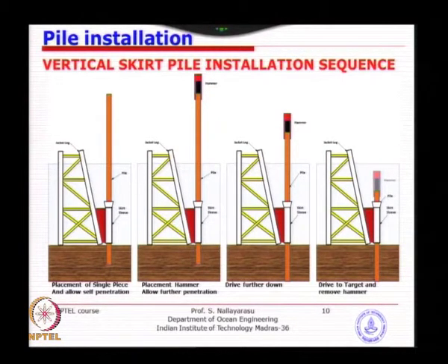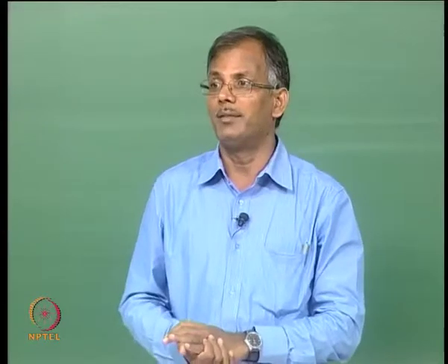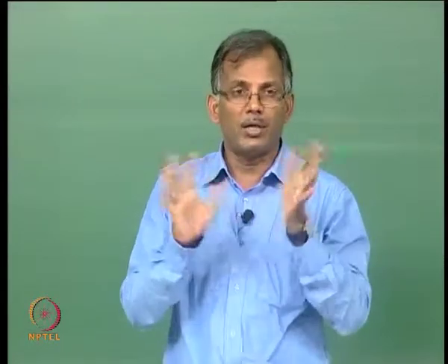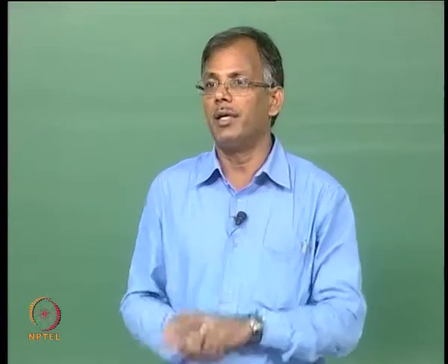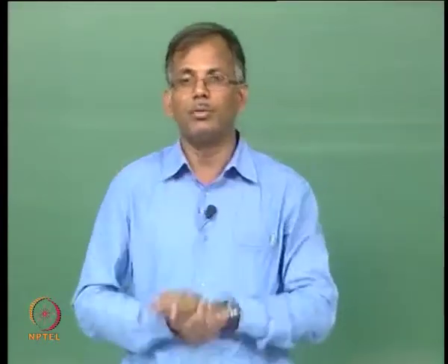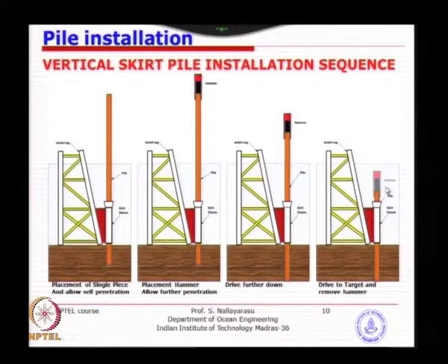That means the hydraulic umbilicals will go from here to the barge itself, because only the barge will have the hydraulic power pack, which will contain pressurized oil. I hope you understand what a hydraulic power pack is. If you go down to our laboratory, every machine has a hydraulic power pack; every one of them is operated by hydraulics. In any underwater conditions, neither diesel nor electric engines will work because of the housing problem. So, mostly you will use a hydraulic pressurized system. So, you will have a connection between this and the barge which is supporting the hammer itself, which you will see if you go back to this.